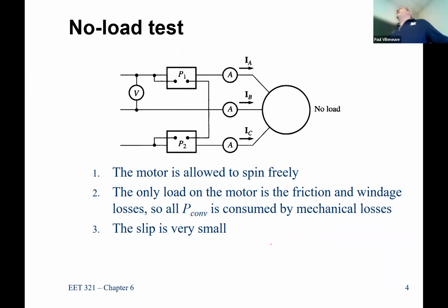So if you have really high power applications, nuclear power plants use hydrogen around their rotor. The reason they use hydrogen is because it's such a light gas, you can reduce the friction and windage losses. I guess it's worthwhile enough for them to do hydrogen, even though hydrogen is explosive. They still want to use hydrogen to provide the cooling around that, and it reduces those losses. So you could do that, but I don't know if they actually do it, because like I said, I've never seen any factory acceptance testing for motors.